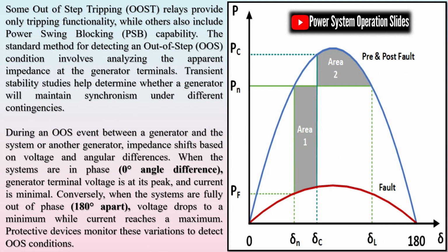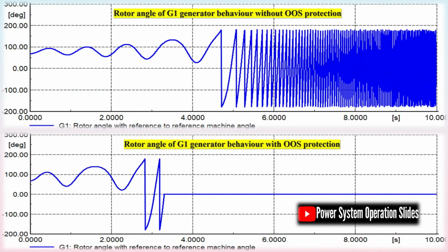The operation of distance relays during power swings hinges critically on the interplay between the relay's polarizing memory and the measured voltages and currents. Modern microprocessor-based distance relays that include frequency tracking are less affected by polarization memory rotation. Additionally, if the line's positive sequence impedance is high relative to the system's impedance, these relays may operate during swings even during conditions from which the system could otherwise stabilize.